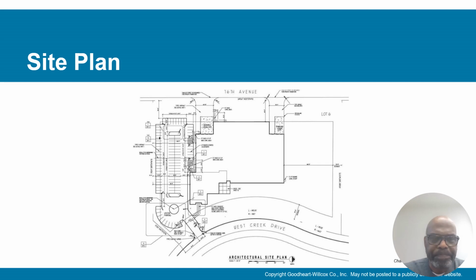But a site plan is usually probably the second page you see, so you can get a general idea about the building and find out how it's placed on that land, but also its orientation. Orientation will determine if it's facing north, south, east, or west. So that would give you a lot of information about the building. It will show you the streets, even the names of the streets, maybe the property line. You could tell how wide or deep the property is from the site plan.